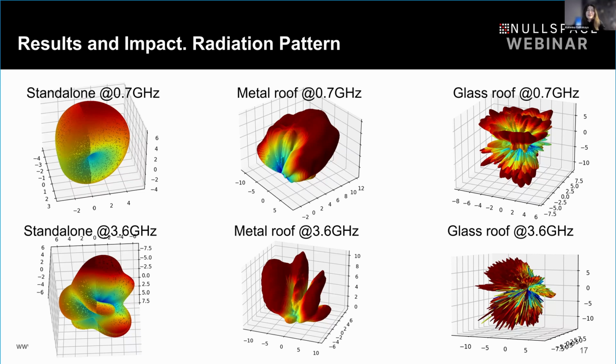If it's an antenna that will be inside, or a wearable antenna, you need to simulate it in that environment. If it's an antenna that will be on a plane, you need to simulate it on a plane. So that's the main point that I always try to show. And unfortunately, still a lot of people don't take it seriously. But I think that with the good pictures that we show here, maybe more people will start taking it seriously, that it actually changes a lot.